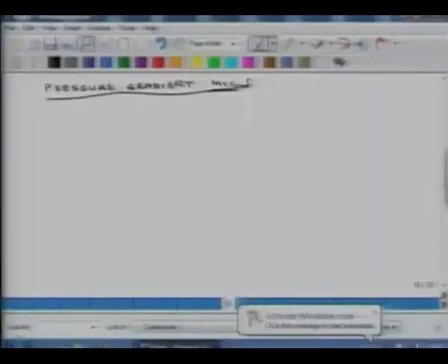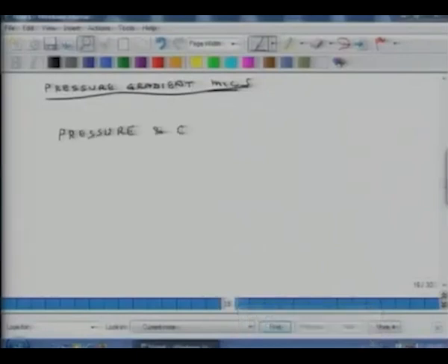But here we saw that the frequency spectrum is boomy at low frequencies and flat at high frequencies. So one has to be careful. As I mentioned earlier, a lot of singers also use it for the special feature that these microphones tend to produce more boomy sound at low frequency. And then the third category we talked about is pressure and gradient mics combo.